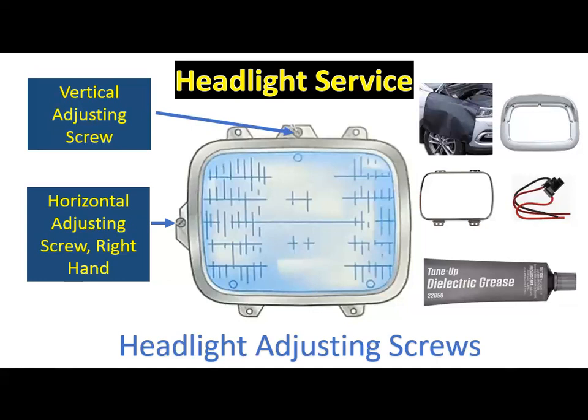Warning for mechanics: when halogen headlight bulbs are illuminated, they become very hot. Do not touch halogen bulbs or attaching hardware immediately after the headlights have been turned off. Do not attempt to clean or replace halogen bulbs when the lights are on.